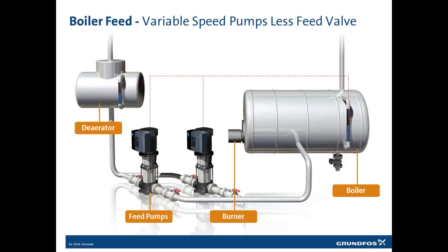And if we have a very low steam consumption, then the pumps will actually run as an on-off control. That works perfectly because the frequency converter can start and stop the pumps many times per hour without overheating. So we can run a start-stop function at low flow, and when the boiler calls for more water, it will go into continuous operation and ensure cooling of the shaft seal.